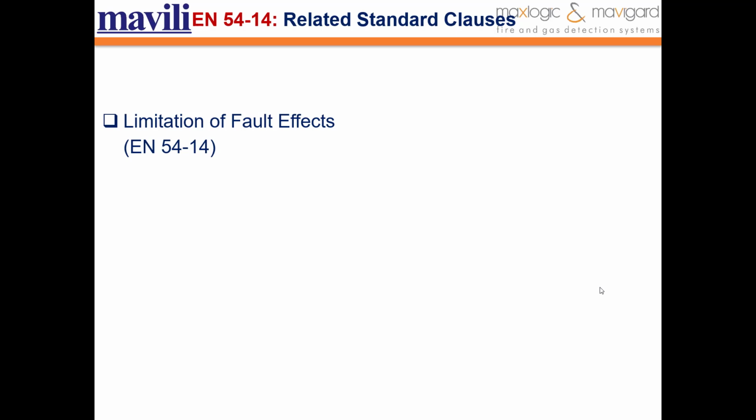Cables without fire resistance: a single fault in the transmission path should not prevent more than one of the following functions from working correctly in an area. Manual start function, automatic fire detection function, and fire alarm function, where at least one alarm device must remain in use.